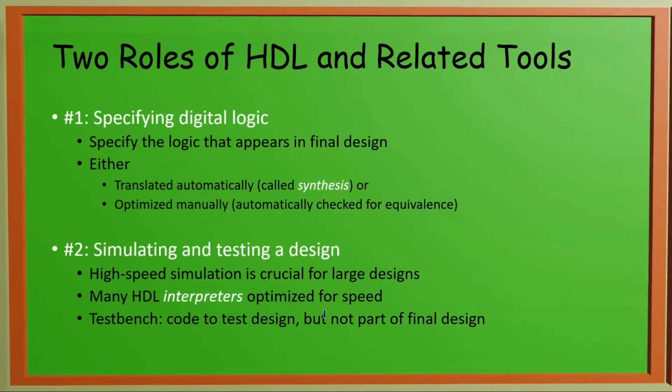So the two main roles of HDL and related tools are, first, we have to specify the digital logic. We have to have a design, and it must be prepared for implementing our final design. For that we use synthesis, and then simulating and testing the design. Let us check the difference between synthesis and simulation.